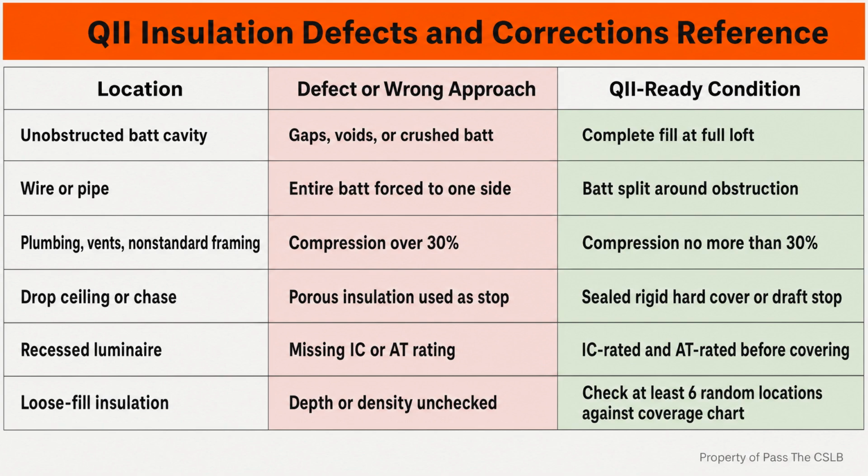There are 2 scope boundaries I want to keep clean. First, under the cited 2025 addition provision, an addition to an existing building that is 700 square feet or less is prescriptively exempt from the specific quality insulation installation requirement. That does not erase other energy requirements, material rules, or ordinary inspections. It means the contractor must identify the applicable compliance path instead of adding or removing verification costs by assumption.